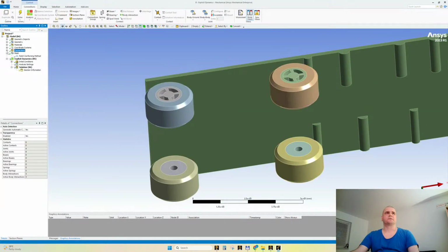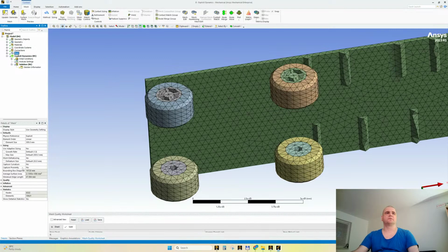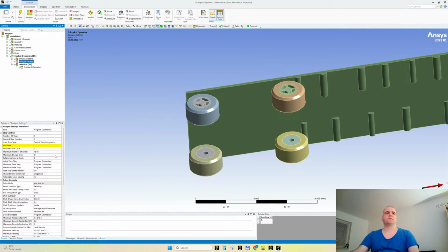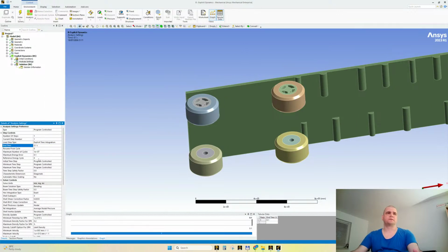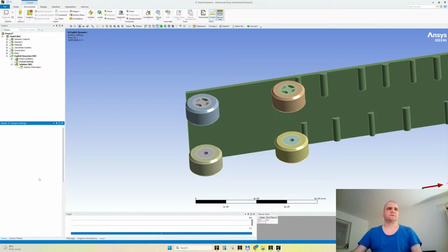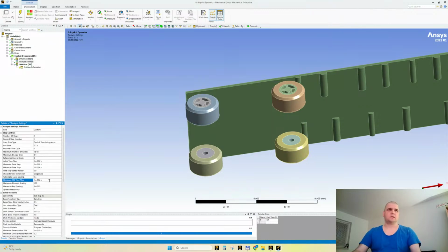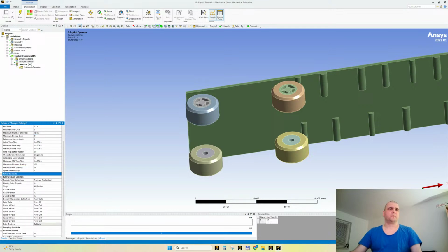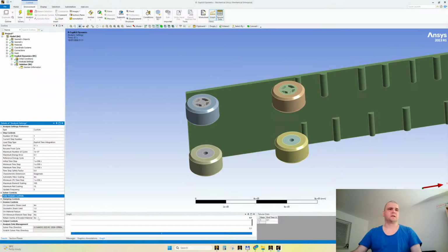So we ignored the mesh, all right. Why? Because I would like to have this number of nodes. I said we're going for 0.1 millimeters, 1e minus 6, 1e minus 9, 1e minus 6. All right, so I advise for mass scaling 1e minus 6 and maybe, I don't know, 15 for part scaling, no for inertia, and 100 for